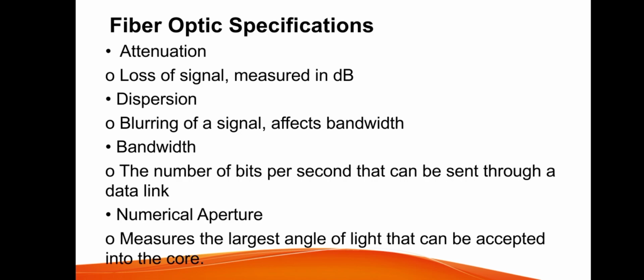The third specification is the bandwidth, the number of bits per second that can be sent through a data link. The last specification of fiber optics is the numerical aperture. The numerical aperture measures the largest angle of light that can be accepted into the core.